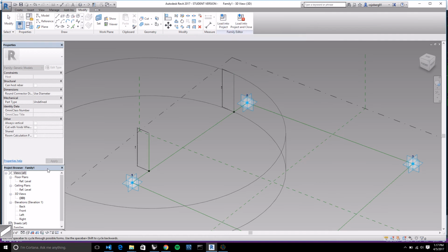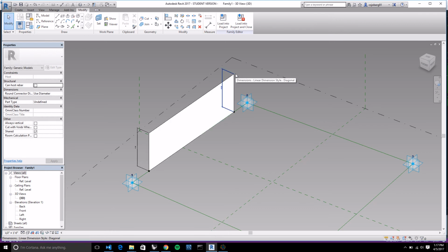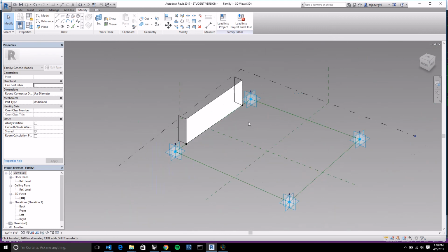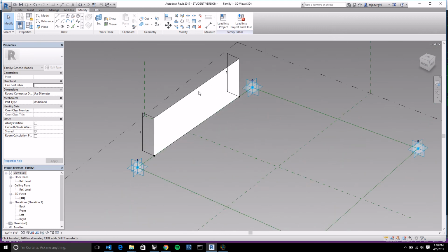And you should see that there's another option that pops up in the bottom corner here. If not, you can press spacebar to toggle through the different options for what geometry you need. And the one we want is just a straight loft essentially between these two lines. I'll press enter. Alright, so you can see now that we've created a lofted plane between these two lines. This is going to essentially be our basic louver.